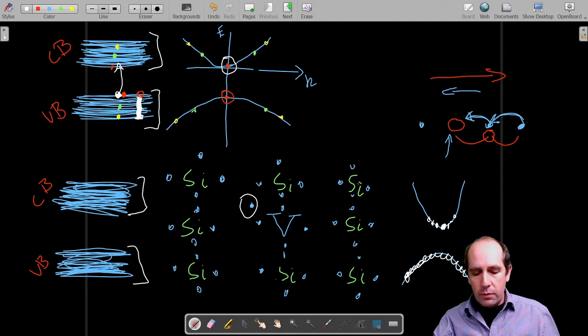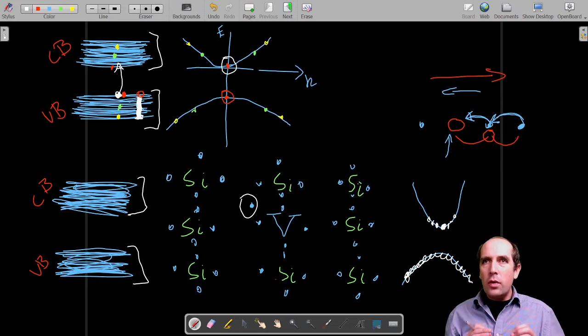So this means that the bands, we can choose, depending on how many of these dopants, as we call these group 5 atoms, how many of these states we populate. And therefore we can control very precisely by just controlling the purity of the material that we use initially. So we put just pure silicon plus a very well engineered, determined amount of group 5 dopants, and with that we can decide exactly how many electrons we want to put per unit volume. And this allows us basically to control the conductivity of the material to whatever we want it to be.